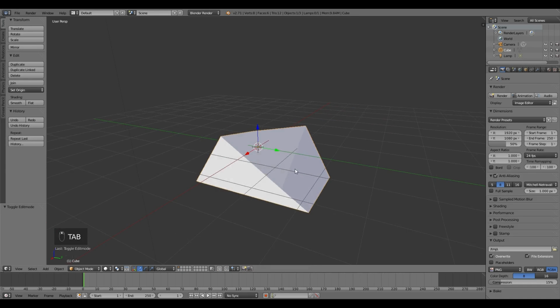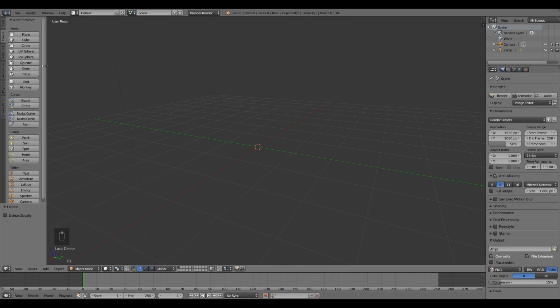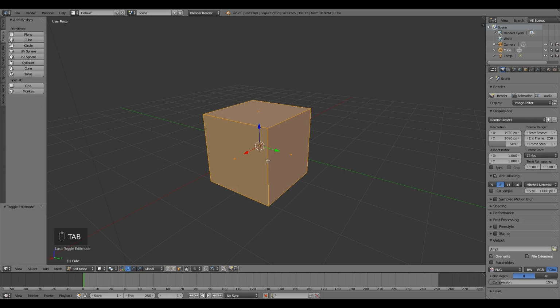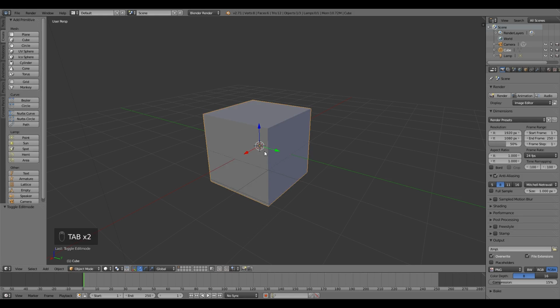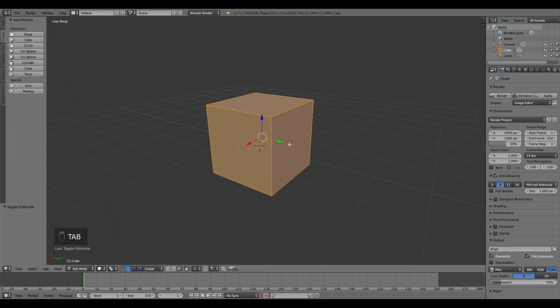And there you go. Now just to quickly test out your skills, let's delete the object. So delete and hit enter. Let's go to create, top left hand corner, and click, we'll just make another cube. So hit cube, you have the cube. Now, remember, if you want to edit it, you first hit Tab, because Tab puts you in edit mode. If you don't do that, you won't get the special options. See, nothing happens. Make sure you're in edit mode, hit Tab, and then you hit A to deselect everything, and then let the editing go.